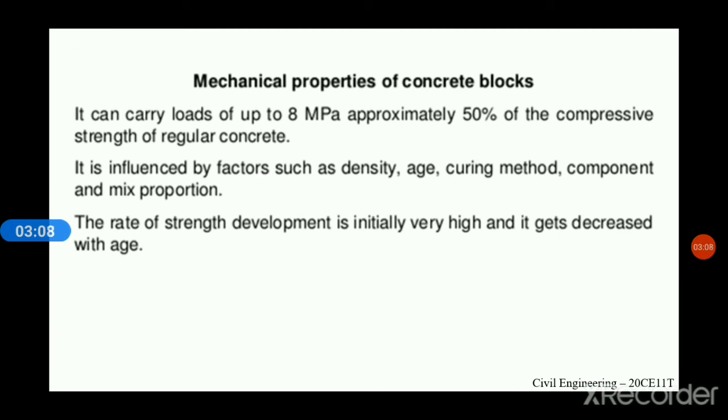So what are the mechanical properties of concrete blocks? It can carry loads up to 8 MPa, approximately 50% of the compressive strength of regular concrete. It is influenced by factors such as density, age, curing method, components and mix proportion. The rate of strength development is initially very high and it keeps decreasing with age.